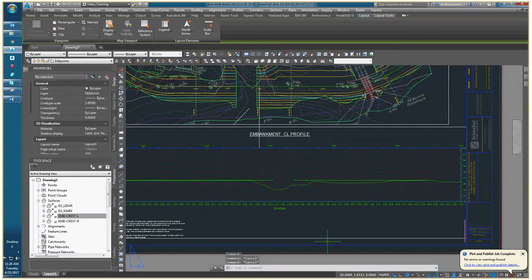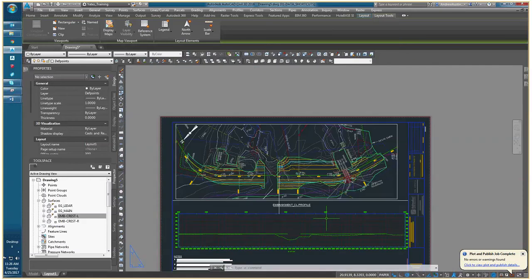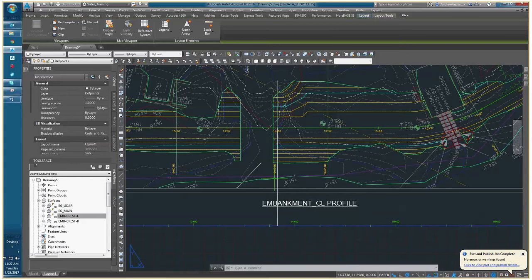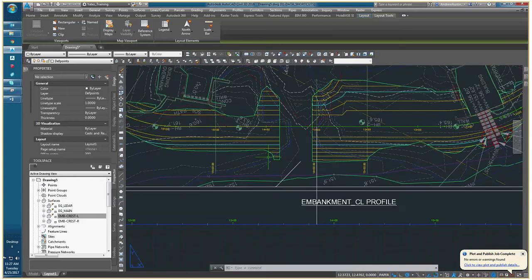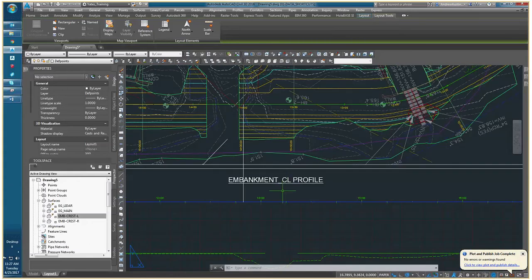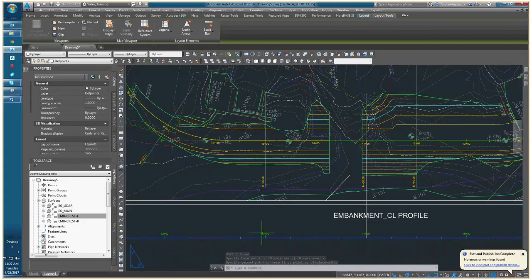And what's great? Alignment in the profile view go in 2 different directions. Yes. Good call, Corey. All right, what Corey just pointed out is our alignment and our profile view are going in 2 different directions. And that's something we would want to fix before we line these things up. Even if I were to get this puppy moved over, 14 lines up with 14, it's not going to line up because 1500 is here and it's lining up with 1300. That's not what we want.